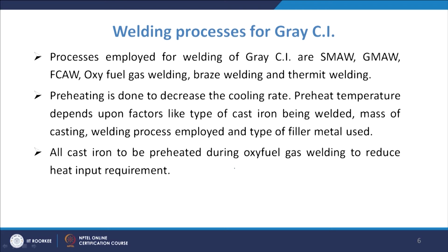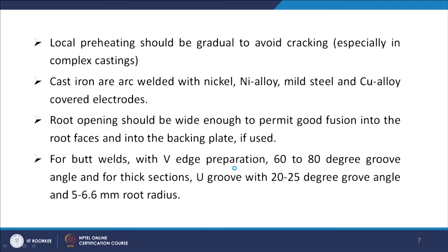Then all cast iron is to be preheated during oxy-fuel gas welding to reduce the heat input requirement. So, in those cases what you do is first of all you do the preheating so that your heat input requirement will be smaller. So, that is what we follow in the case of cast iron welding. Then we have already seen that local preheating has to be gradual, so that cracking is avoided, especially in complex shapes of castings.